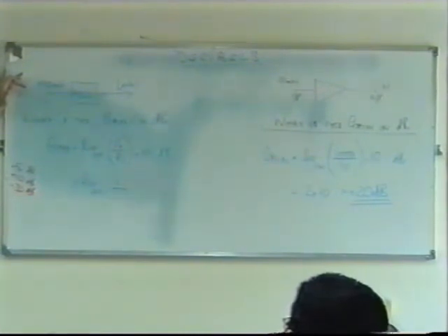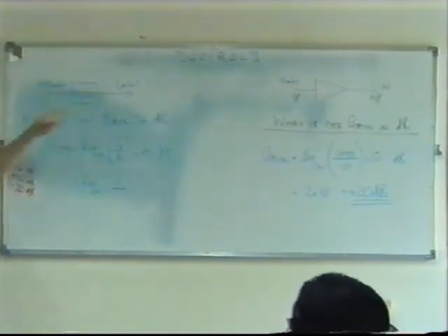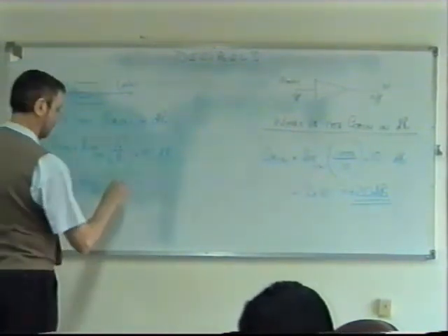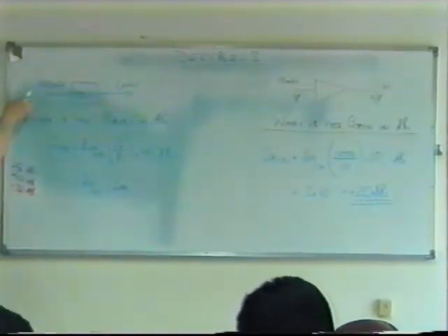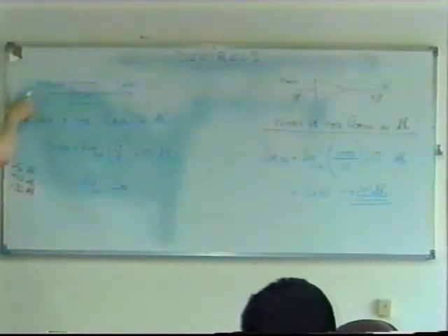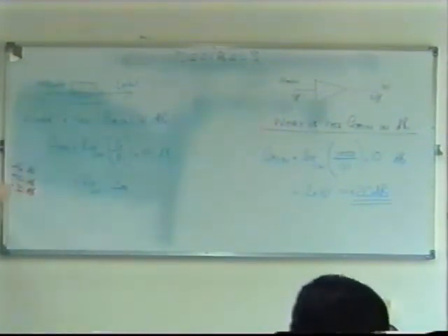Now these sort of calculations you should practice and practice and practice, because this is the sort of thing you should be able to do quickly in your head. But even if you used a calculator, you've got to bring these to the same units somehow. You can bring them to watts, microwatts, milliwatts, whatever. You're going to get the same answer, as long as the units are the same. In my example, I said I'm going to bring everything to microwatts. So we've got 1 microwatt divided by how many microwatts here? 100,000, because there's 1,000 microwatts in 1 milliwatt.